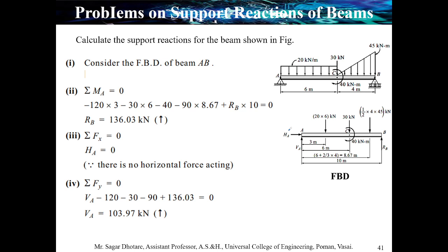Okay, so once again you can just recall the total process. First, we need to draw the free body diagram. We have to convert the loads like UVL and UDL into a single point load and identify the location of these loads. Then next, based on the supports, you can find out which kind of reactions are occurring at a particular point.